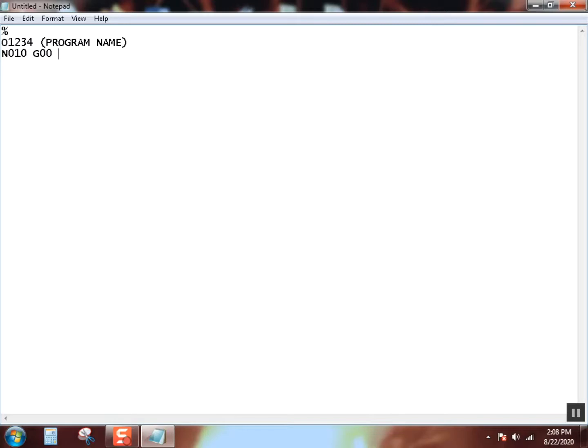Next thing I want to do is tell it what plane we're going to do our arcs in. Now planes just mean what movements we're going to make. Bottom line, you're just always going to put a G17 there. Remember, they're going to get bigger. They're going to start at G00, then G17, then continue. All right. Next one should be a G20, which means we're going to program in inches.